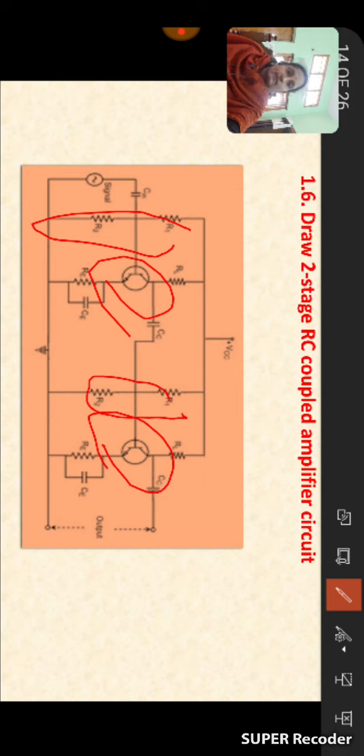If it depends on those parameters, automatically the leakage currents will be increased and the self-destruction of the device occurs. So, to protect the transistor from self-destruction, here we are using the resistors R1 and R2 across each transistor.